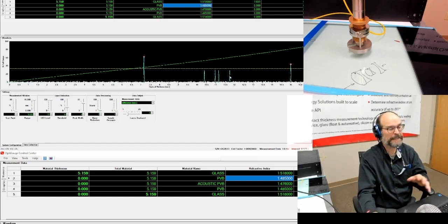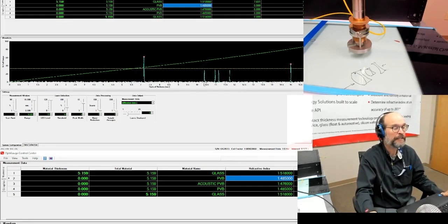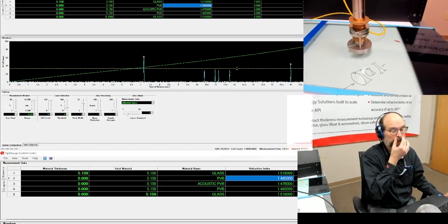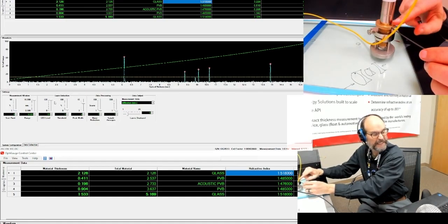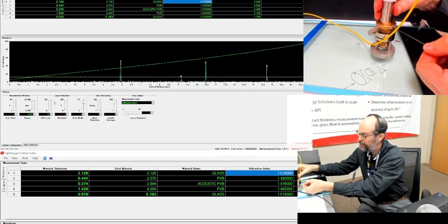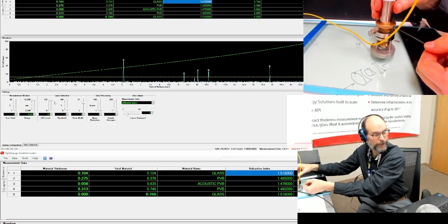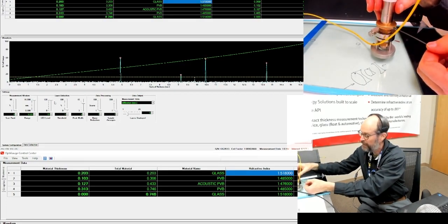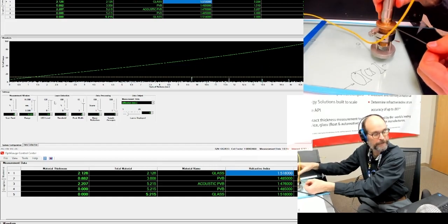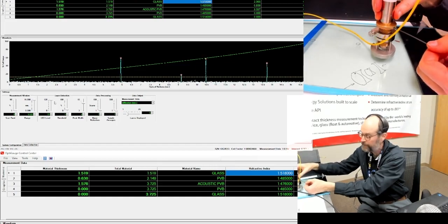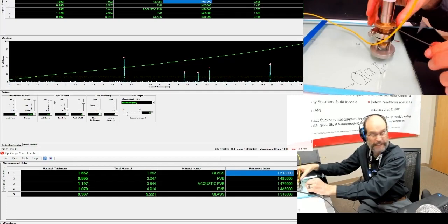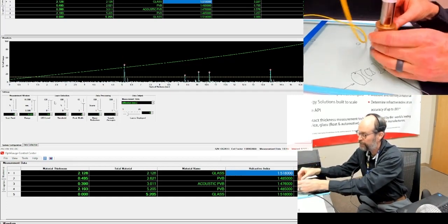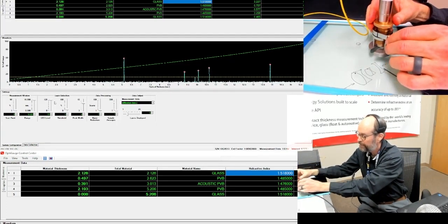Because what happens is it doesn't see these peaks anymore, because I brought it above them. See where I put in the Allen key? That allows you to raise or lower the gross height adjustment. Now what I would say, with the 25 millimeter, is just go ahead and let it bottom out and tighten it down. And then you'll do all fine adjustment from there.